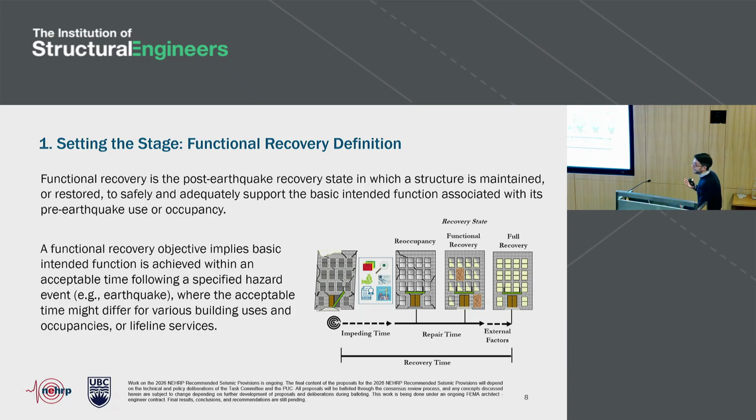So what do I mean when I say functional recovery? This is a definition that we plan to include in the provisions. Functional recovery is the post-earthquake recovery state in which a structure is maintained or restored to support the basic intended functions associated with its pre-event use or occupancy.